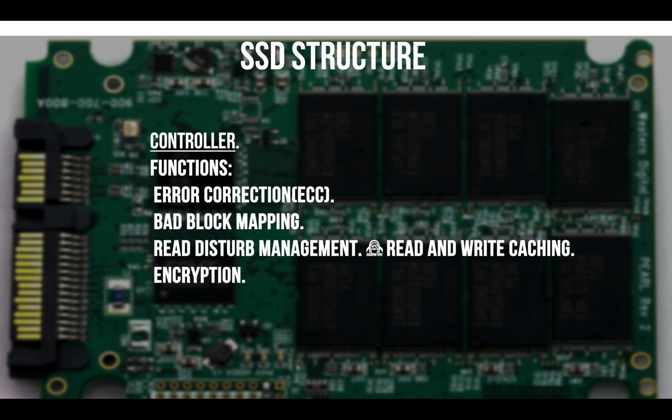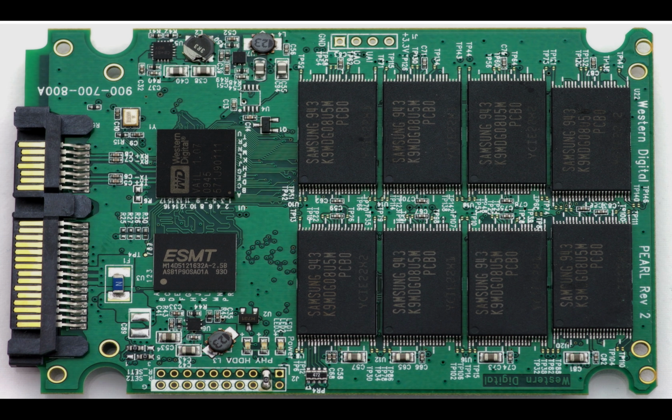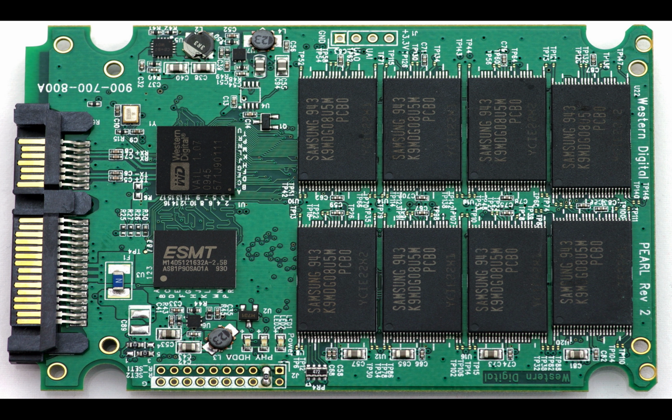Every SSD includes a controller, for example, an embedded processor that executes firmware-level code, and it is one of the most important factors of SSD performance. So let's talk about its functions. First, error correction, then bad block mapping, read disturb management, read and write caching, encryption. So here it is.